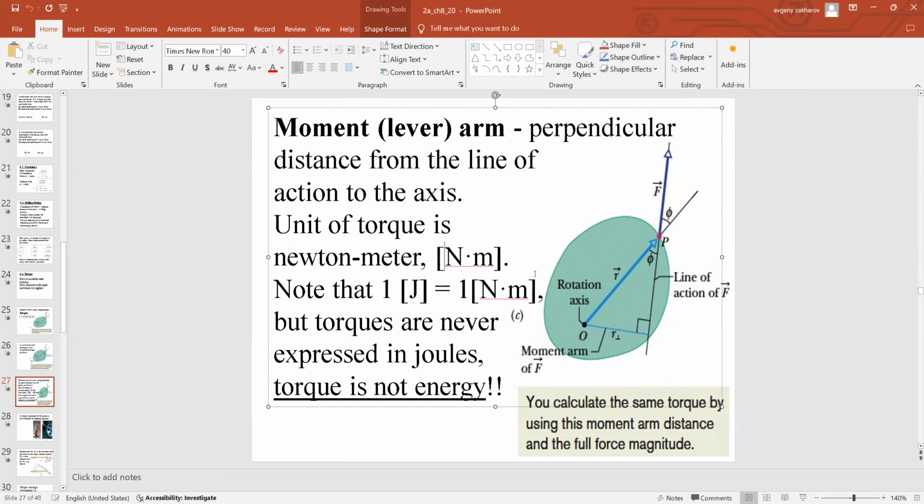Units. Units are what? You have force and you have distance. So it's Newton and meters. And remember, we had newtons times meters for joules, and that was good for energy and work done. No more of that. It's only Newton meters as is. Do not say joules. Joules are reserved for energy and work, and Newton meters are for torques.